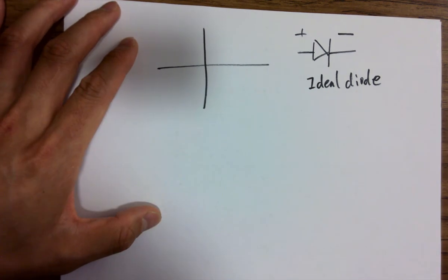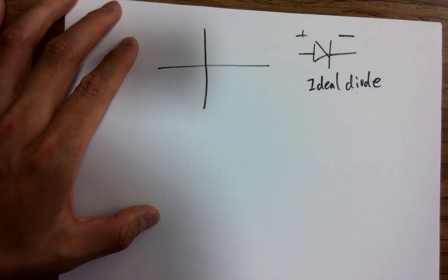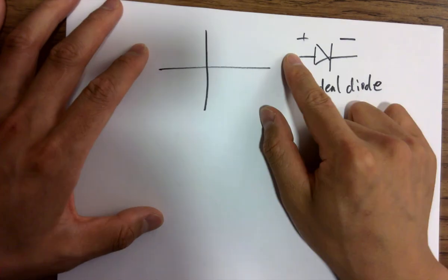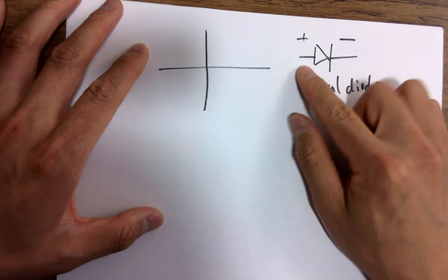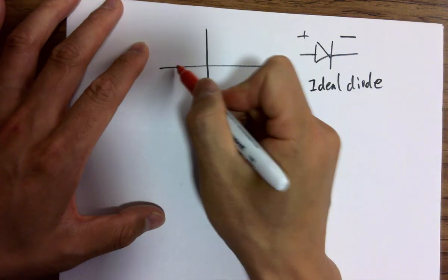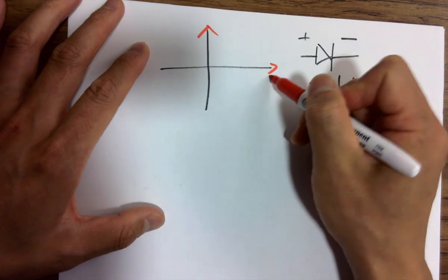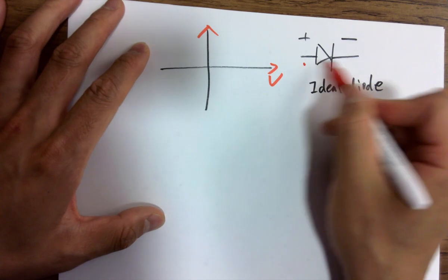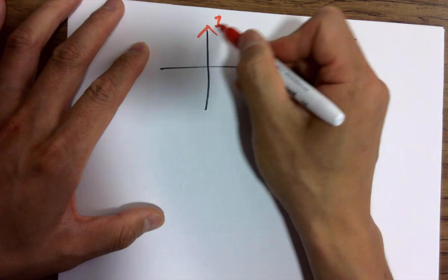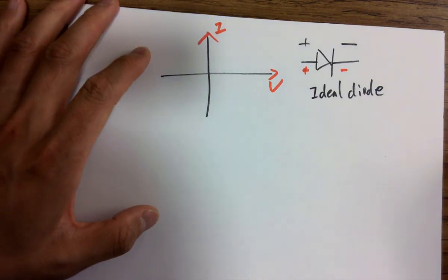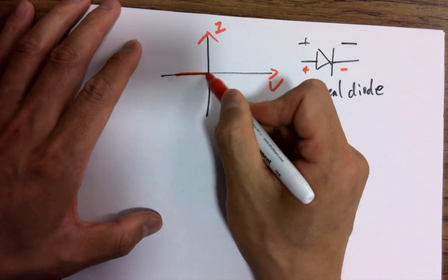Ideally, when people design a diode originally, what do they want? They want to conduct current in just one direction instead of two. So they are thinking that whenever I have a voltage trying to forward bias it, I'm applying it here, I should get a current, and there should be no built-in resistance or capacitance. So ideally, it should be this.